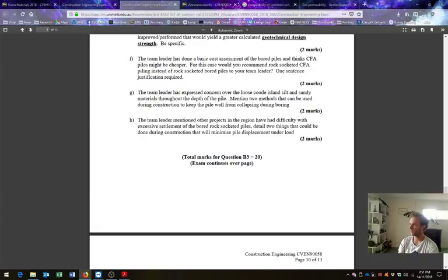Okay. So for CFA construction in the middle of a river, should we use a cofferdam to prevent water contamination? You should do something, for sure. A cofferdam is one answer, yes. Another answer is a steel tube and CFA within that steel tube. Both are correct.